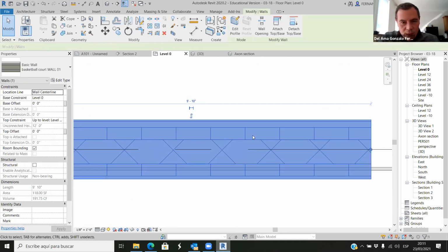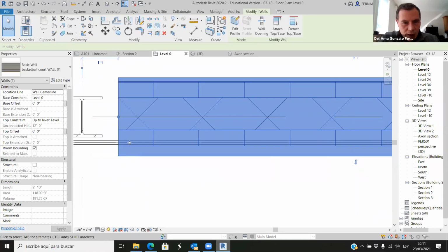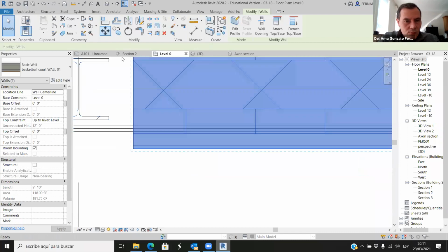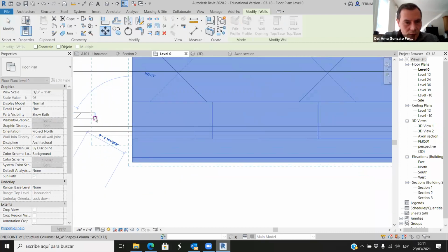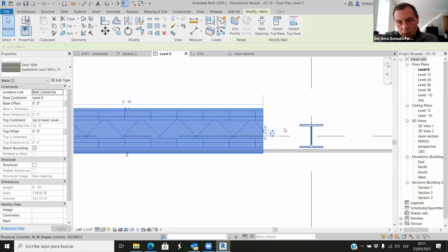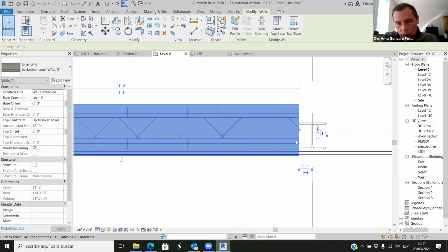By pressing the space bar, there you go, because now this is the air layer, thermal insulation, concrete masonry unit, thermal insulation, and the gypsum board or the plywood or whatever. Remember that we wanted to do this, okay? And then I drag it here.